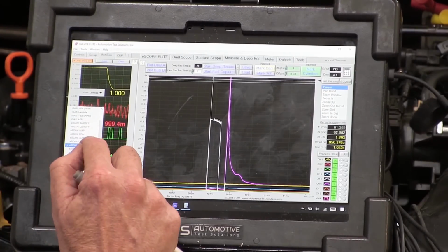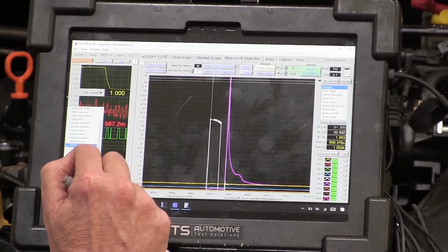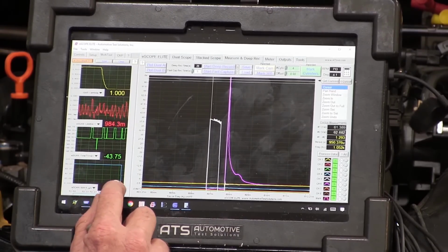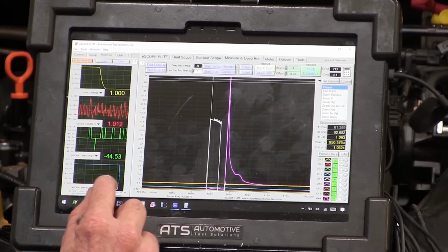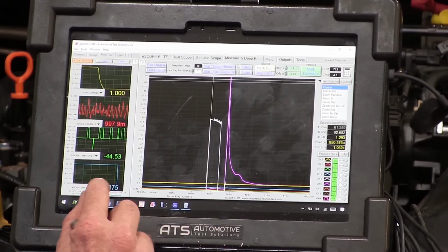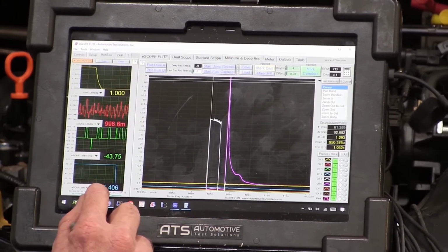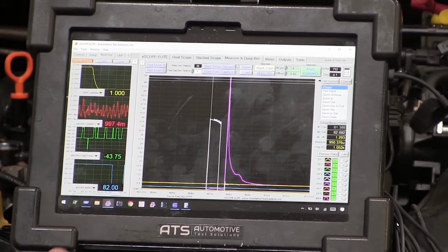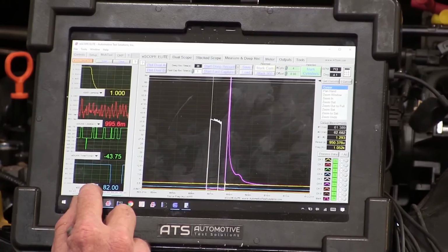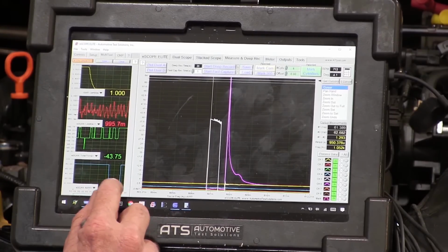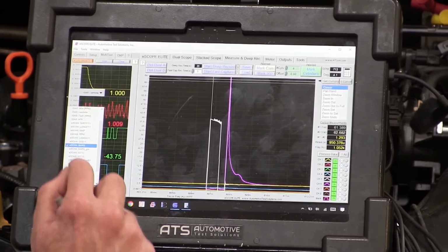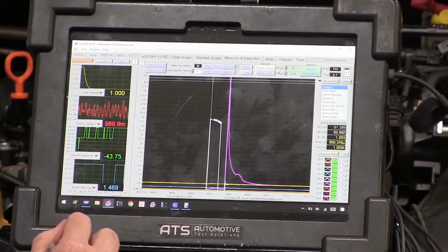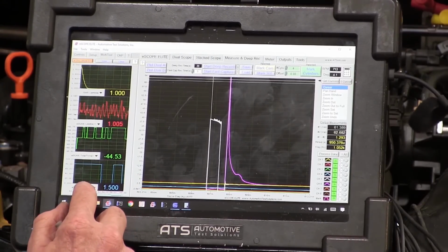Now the main thing that would get me here would be the gram weight. I'm only at 1.3, 1.4 grams, and this is a 1.5. So the weight of air is entering, right. Now one of the other things that might get me right here is the baro. I'm at 83 kPa because I'm a mile high, so the baro is right. The baro is right and the grams per second, so the two basic air inputs are correct.